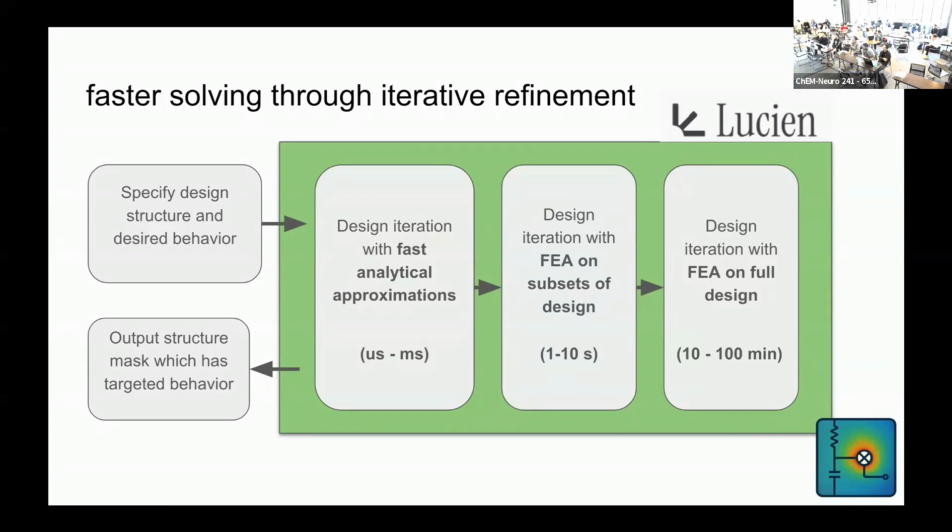We begin by coming up with the parameters that we want to target, things like resonance frequencies and coupling quality factors. We then build an MCP tool that can do fast analytical estimates that might not be accurate, but they're in the right ballpark of what sorts of lengths and widths we need in our design. We have our large language model optimize its design under this approximation.